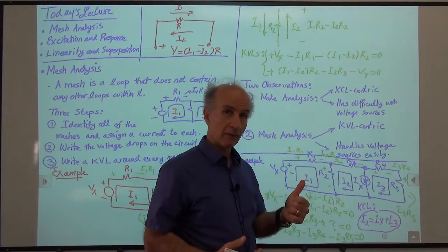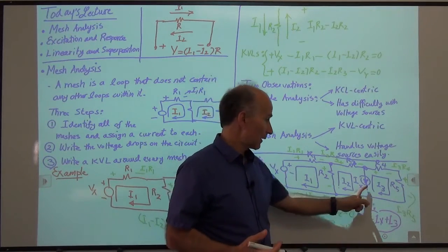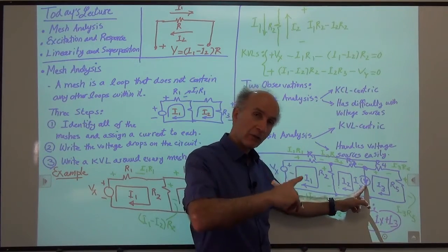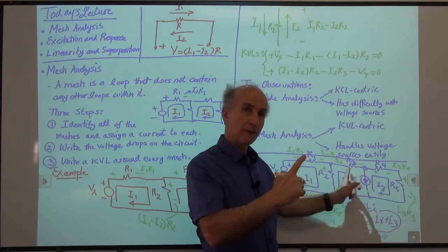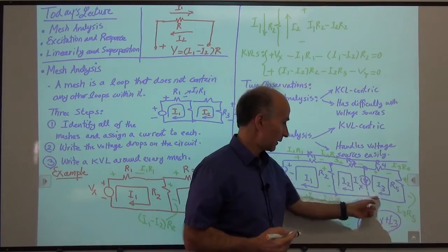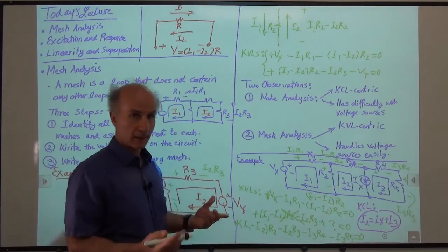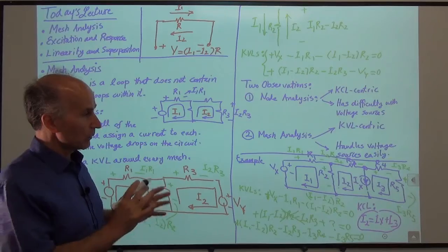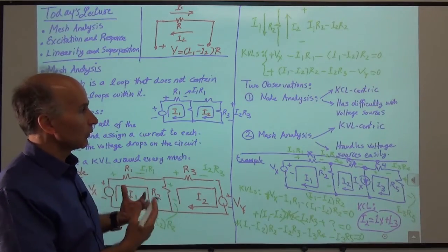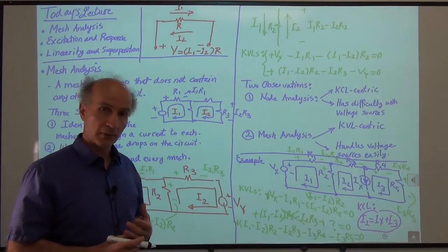And because we lose one KVL, we look for a KCL involving the current source and the currents of the two meshes that share that current source. So it would be this current, and this current, all at this node. All right, so that's the procedure. That's the only issue we have to worry about when we are performing mesh analysis, but otherwise the steps are pretty straightforward.